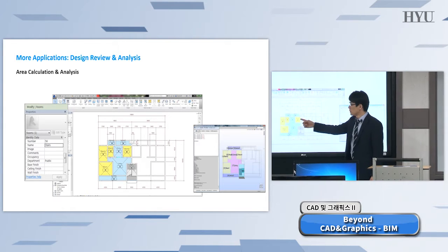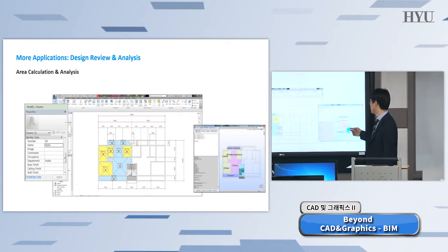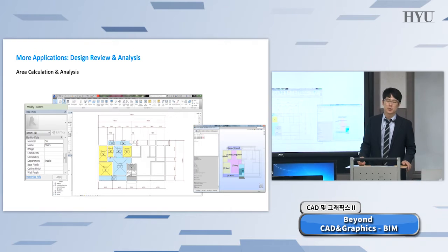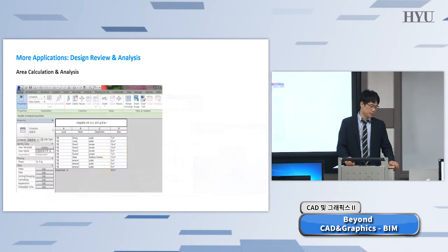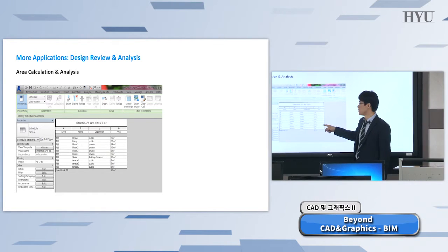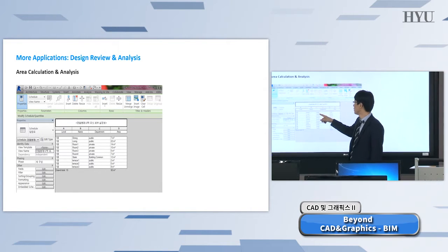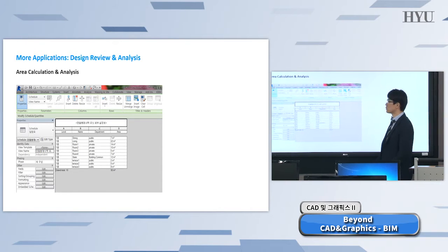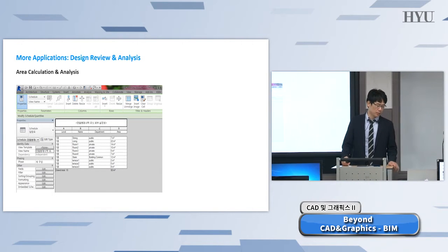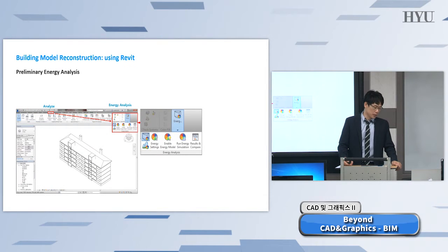So different color scheme can be displayed even in this building model, as well as some additional application, BIM application for analyzing spatial allocation issues like this. They provide precisely computed area numbers. For example, dining room on the first level in public department could be 7 or 22 square meters, and so on. Very detailed area calculation and analysis can be conducted.